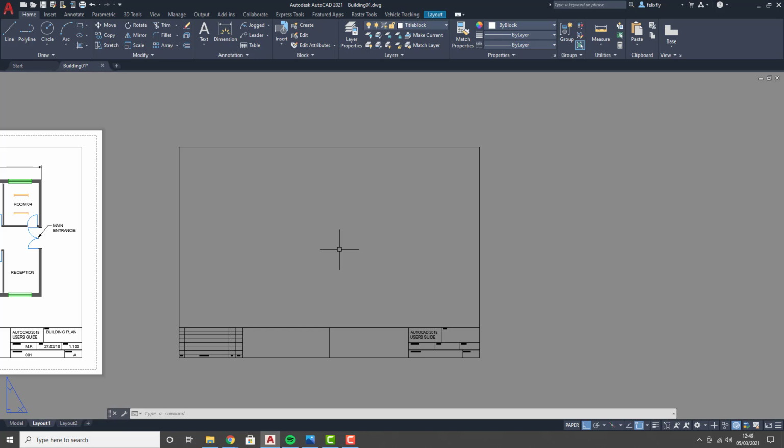So you might be able to see a 20-meter high building and see the whole outline of that through a window frame that's only 1 meter tall. How does that work? Well, the building's far away, so you've zoomed out, if you like. The building is set way back, so through your 1 meter square window you can see a 20-meter building. If you remember that, that's all you need to know. That is how a viewport works.